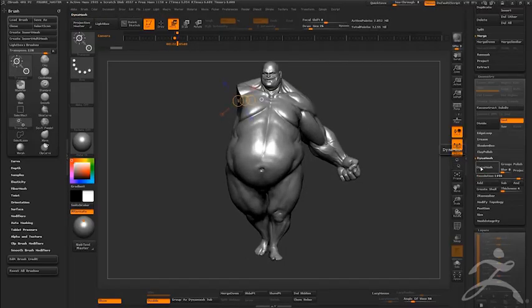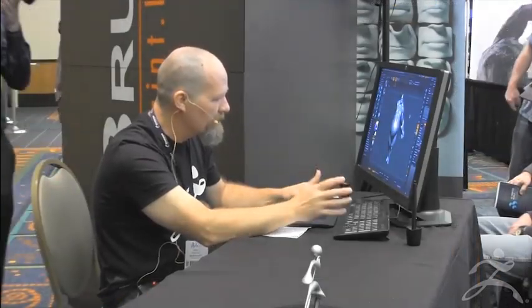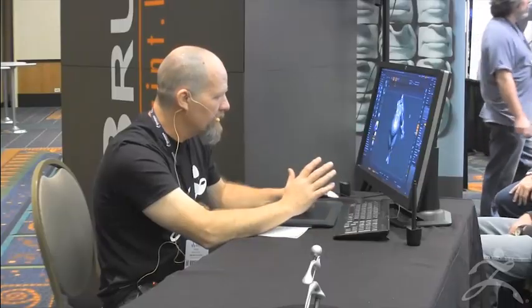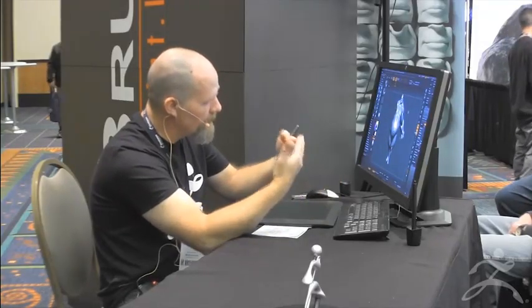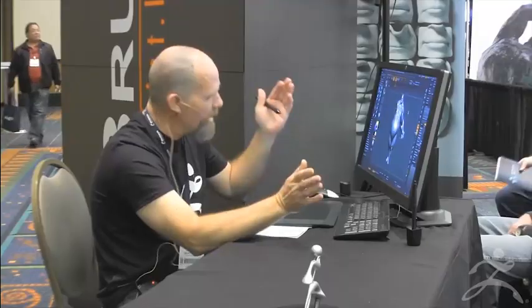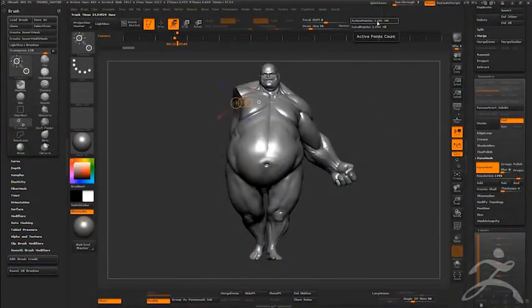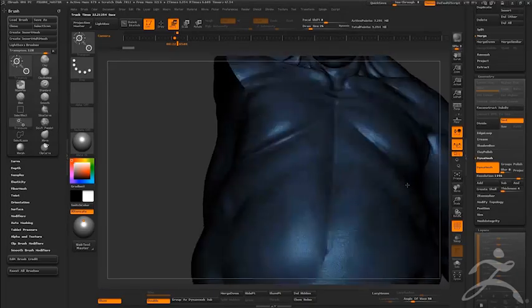And all I have to do is click this button, and it's going to calculate and dynamically remesh this thing. So if there's any stretched polygons anywhere, it's going to get rid of them. Surface distortions, where meshes are interpenetrating or intersecting each other, it's going to get rid of that interior mesh that's not being seen. Now my point count is over 3 million, and if I turn this back on, you can see how insanely dense this mesh is.